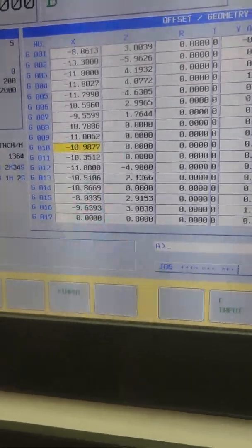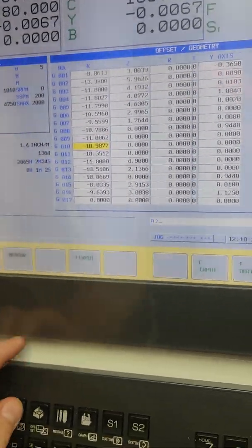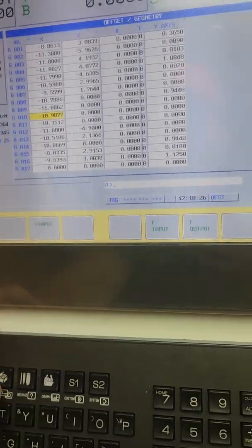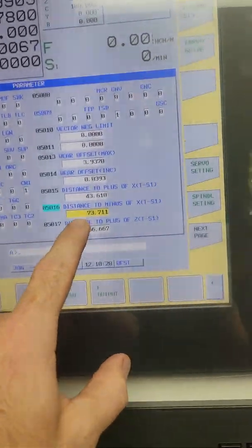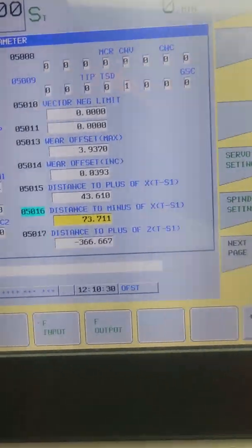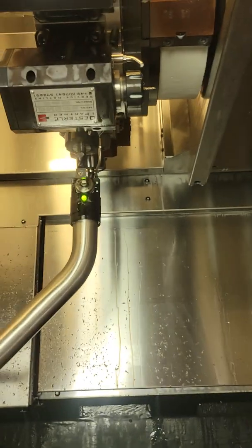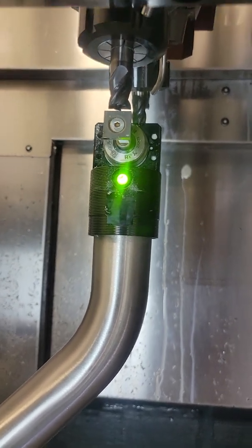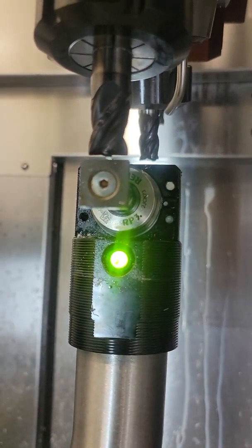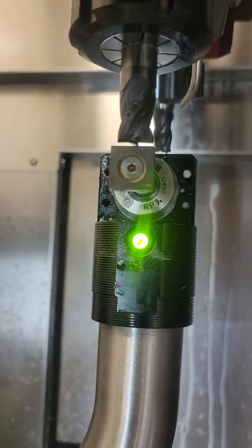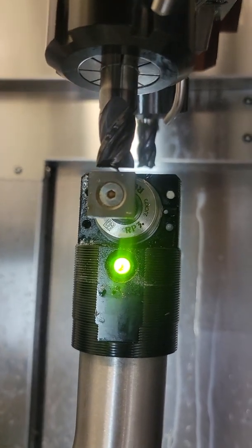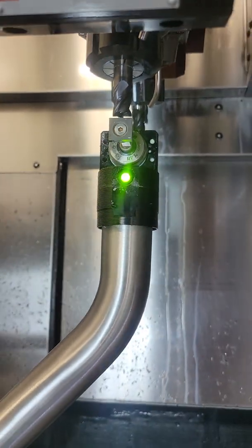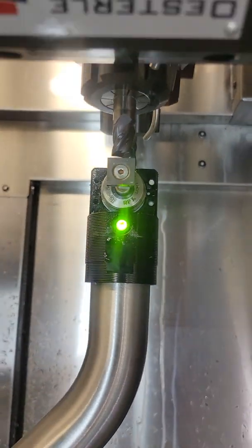Right? So if I'm within 1 thou or 2, that's okay, because tool pressure, it's going to change tool by tool. So now I have my parameter that I've changed, and that's my new number, and I have tweaked the position that it calculates when touching off tools only on the positive side. I'll do the other sides as I need them, but this is the one that was getting the most use, so that's what I did.